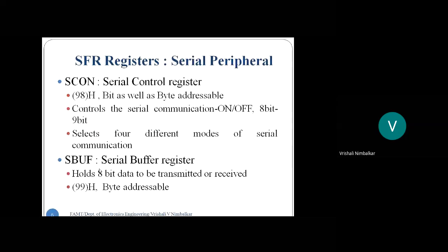Internally, there are 2 SBUF registers, and the SFR address of both the registers is 99 hex. So we are going to have two hardware registers inside. The name is SBUF. They are going to have the same address, but one SBUF register will be activated by the read control signal and another SBUF register will be activated by the write control signal. See why this is so?